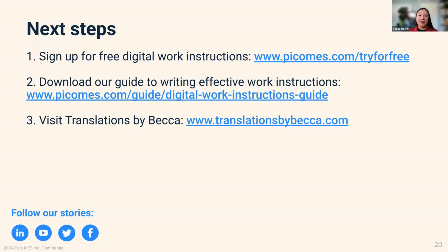I'm huge on feedback. I don't care who you are, how great you are at writing procedures. If you're not the one running the equipment, you are not the final say. The person who is actually running the equipment is the only person who can say whether the procedure is effective. And you want that feedback as quickly as possible, which is why even a year can be quite a length of time. I would try to go sooner than that, but people are going to forget where the pitfalls in the procedure are because they'll remember how to run that equipment. They'll forget, oh yeah, it doesn't actually tell you to flip the blue switch. So you want to get that feedback on a regular basis, at least annually.